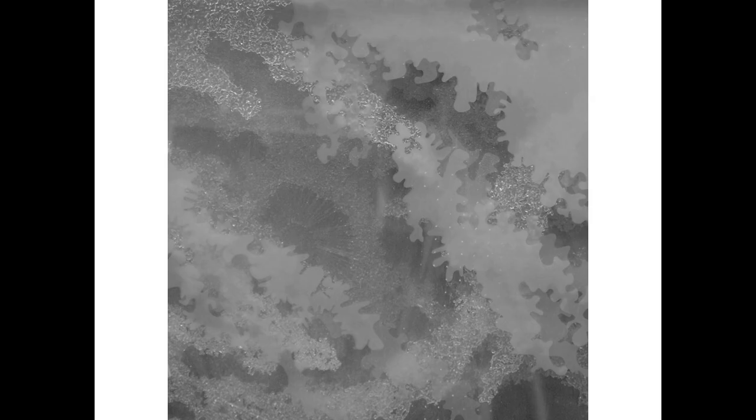And just as an aside, you can laminate anything you like between layers of glass. So if you're interested in the texture of glass or in the way that it transmits light into a building, this is actually wax. This is 2 layers of glass bonded around wax. On the left we have layers of glass bonded around very fine cotton, and of course you can print onto glass, and it's a sensible idea to print onto the inside of the glass, so that when you bond it together, whatever you've printed is permanently there.